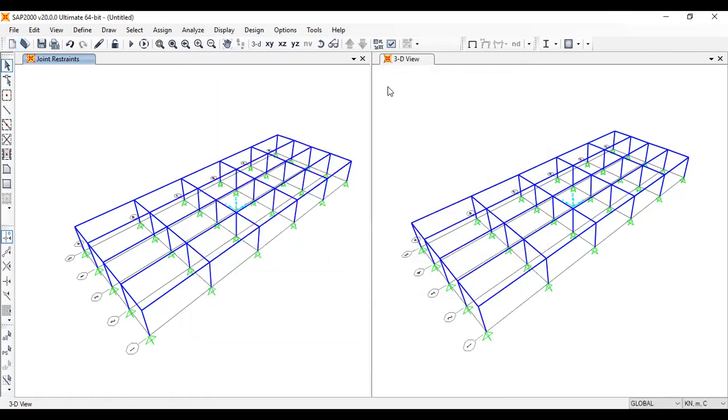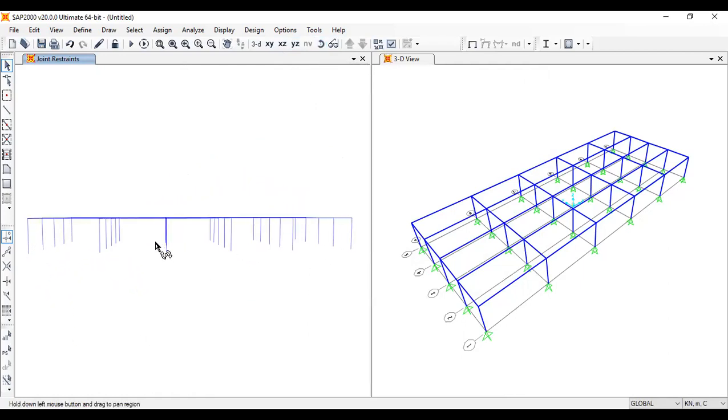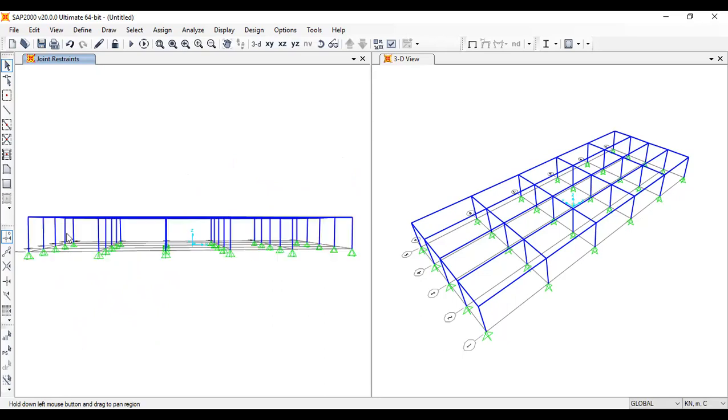But still we have to assign that, right? We have to assign those values. So how we are going to do is, we need to separately select the columns. So how do I do that is, I can rotate this view. So if I select from left to right, you remember it's like AutoCAD, there will be only full element getting selected.